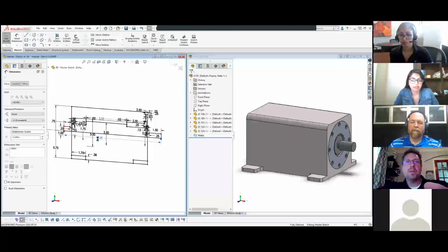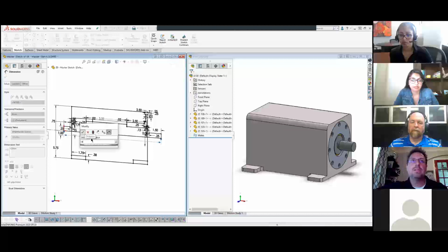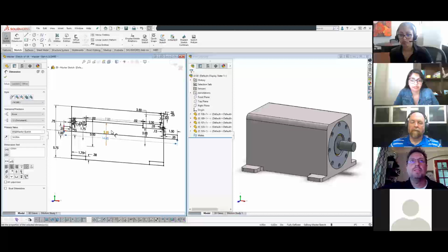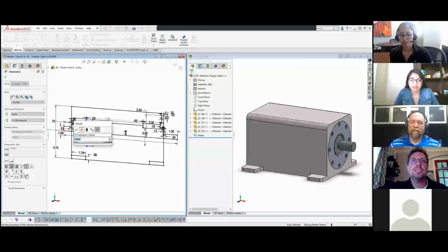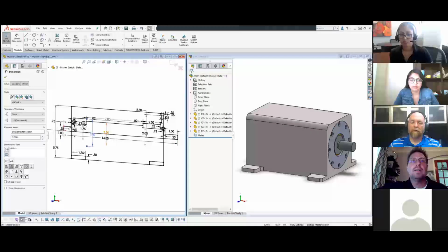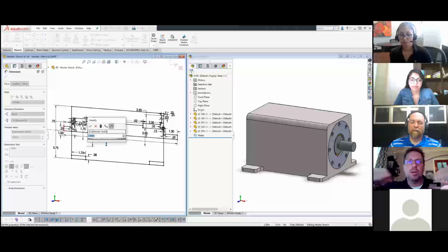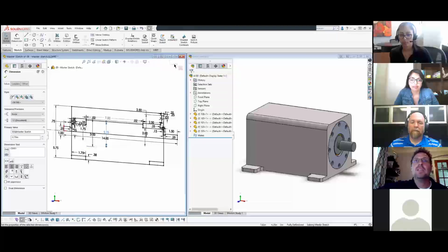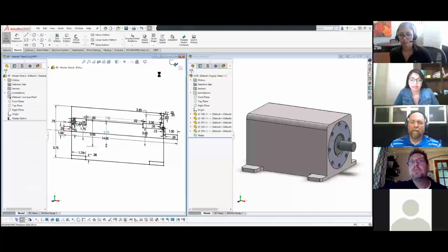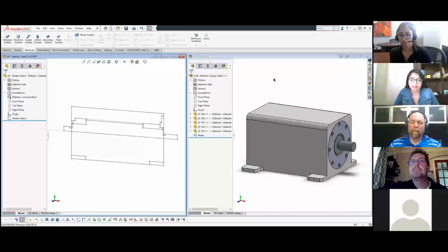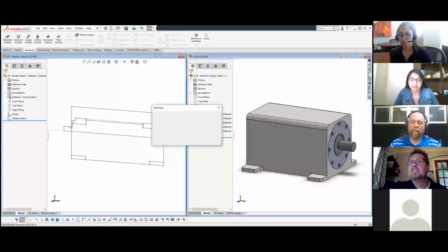We'll make it 14 millimeters long. This is a little bit wider there. You'll see it change. And let's change, not that 3, let's change the 2.5. We'll make it a little bit taller, 2.75. There you go. And then as I finish out of the sketch, all I have to do is select into the assembly, and you'll see it change in just a bit.